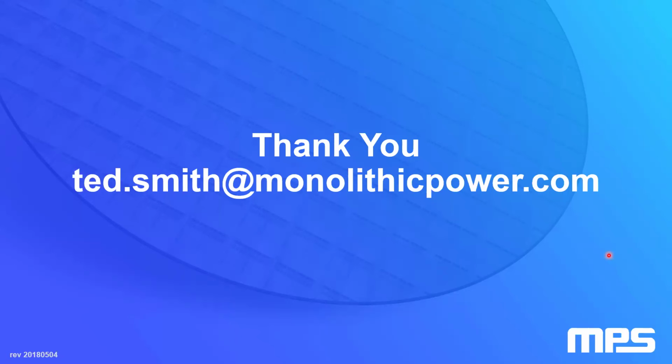You may be able to find a webinar, or at least an article written by me, on spin axis and how it works. But our position sensors, because we use the so-called spin axis and it uses time to digital conversion, we don't get a good source of magnetic field strength like you normally would with parts that use arctangent and A to D converters. We don't have an A to D converter in our sensor.